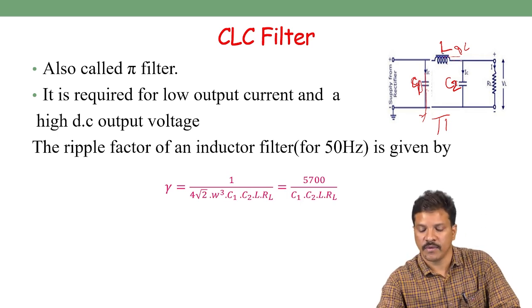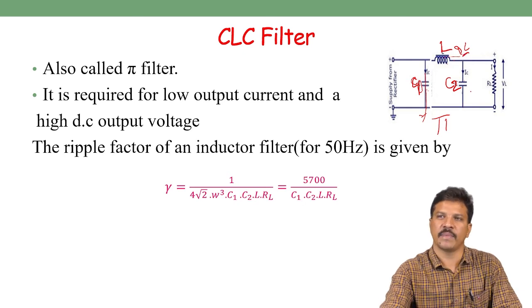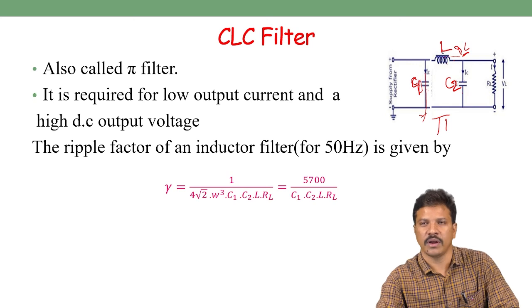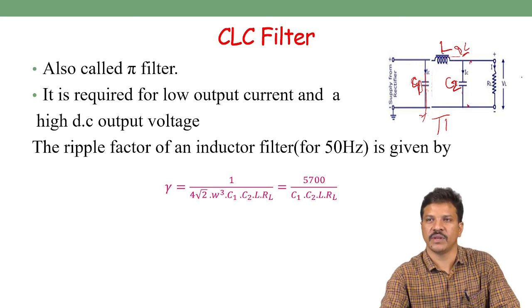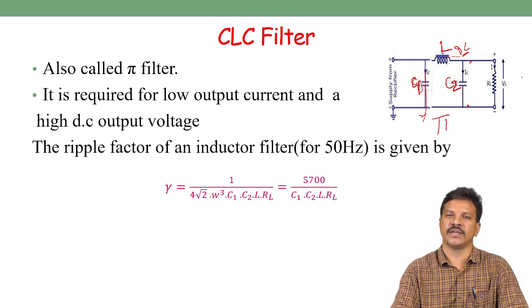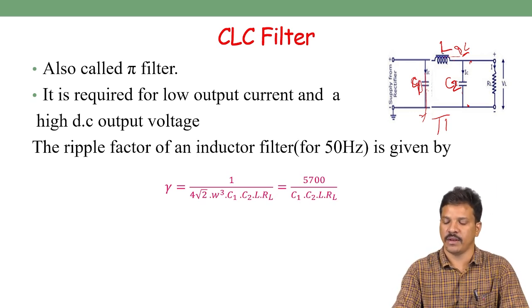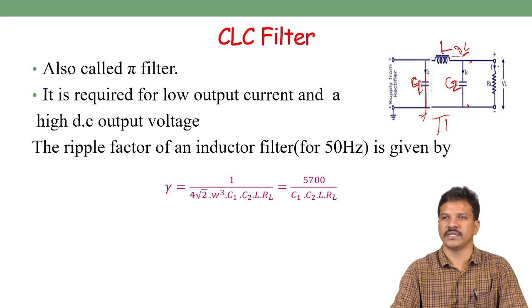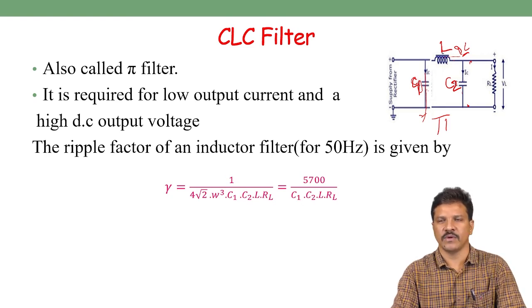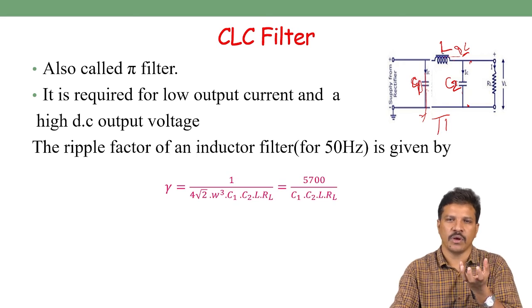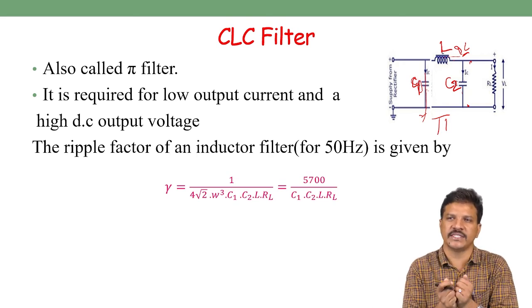So again, whatever the output coming from the inductor filter is passing through the capacitor. So we can get more DC component across the inductor capacitor, which will be parallelly connected to the load resistor. The same DC output will get across the load resistor. Here we need to remember that the first capacitor already allows the AC component and filters and captures the DC component.